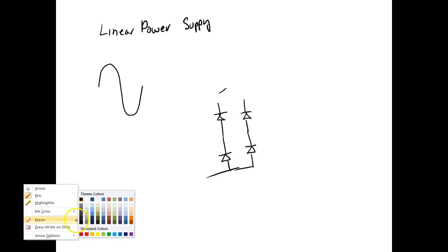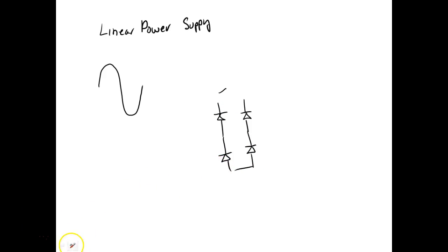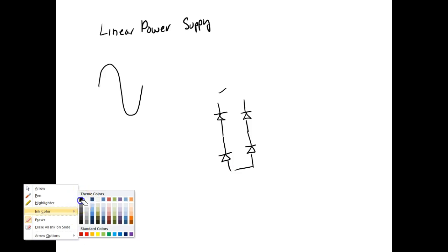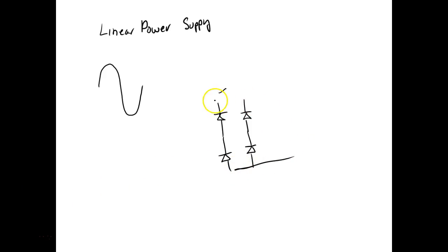So a diode, and we talked a little bit about this, a diode only lets current flow in one direction, right? Everybody understand that? Okay. So these guys are in your alternator on your car. Your alternator puts out AC, right? But your car runs off of DC. So it's got to convert it from AC to DC.